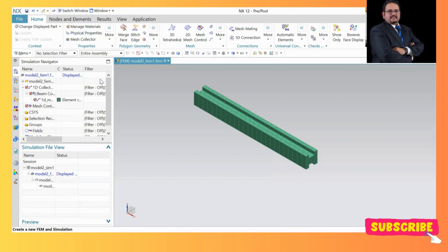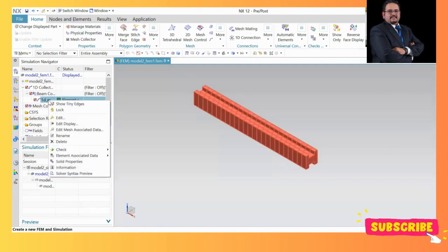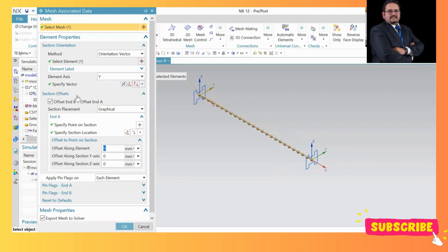So if you want to keep it like that, then you keep in your mind that your beam is oriented like this, right? Which means when you apply a load, it will be applied in the Y direction, right? Because this is how the beam will come. Otherwise, if you want to make it with respect to the right configuration, you again right click, you click edit mesh associated data, and this is the elemental axis.